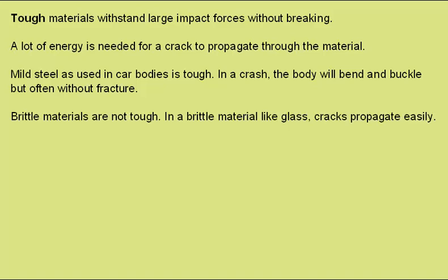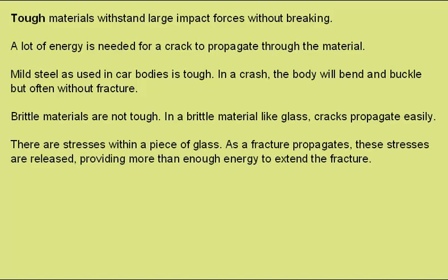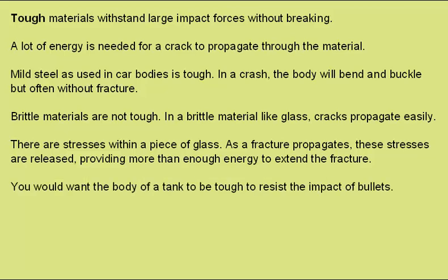In a brittle material like glass, cracks propagate very easily. In fact, in a complete piece of glass there are stresses. As a fracture propagates, these stresses are released. The energy released by the stresses provides more than enough energy to extend the fracture. That's why a piece of breaking glass almost explodes. You would want the body of a tank to be a tough material, and so resist the impact of bullets.